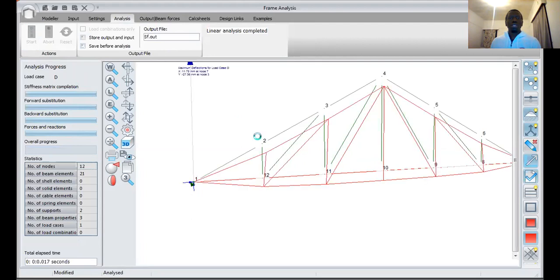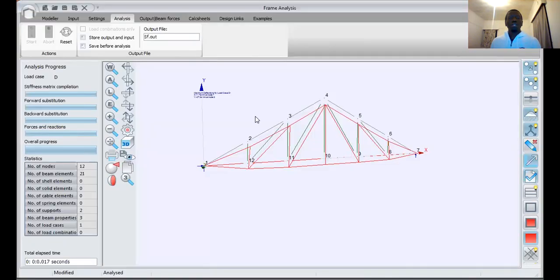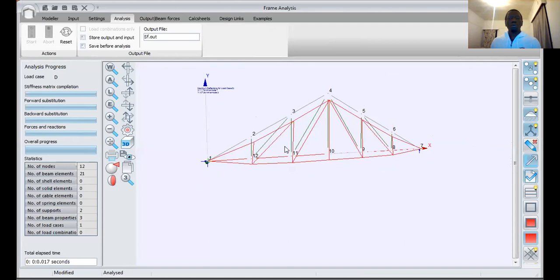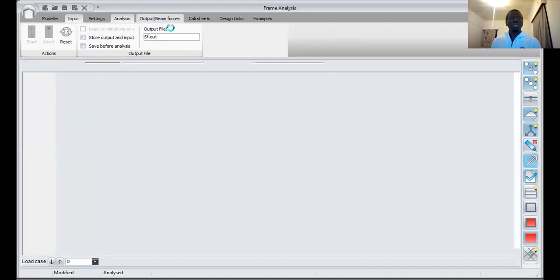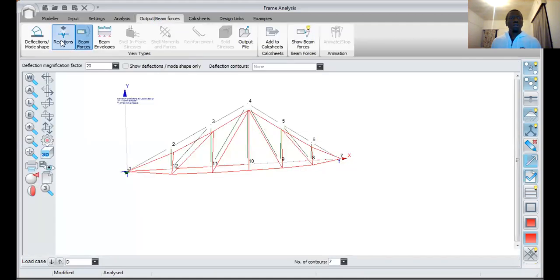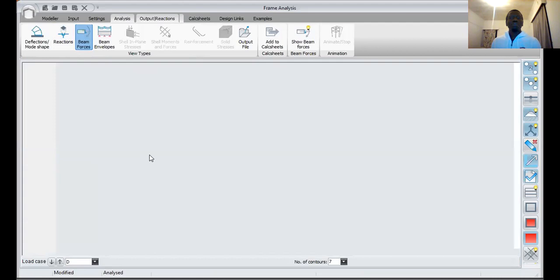Okay, there you go with the deflections again. When we start doing things like portal frames, we will be interested in the deflections. Now we're not so interested in deflection, because this is the beginners exercise, but at some stage we shall be interested in deflections and how much they are, in which direction, and things like that. Okay, you've got your output of beam forces, basically the same drill. You can look at your reactions, this time including self weight. Obviously you expect them to be bigger.